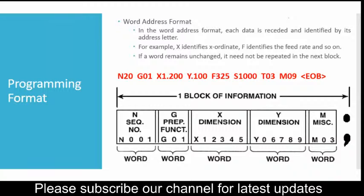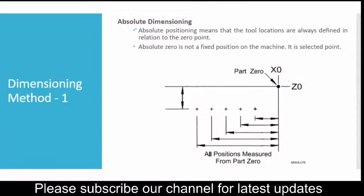Okay, now let us jump to the next slide. Now before starting, suppose I have to change tool. So every time offset measurement? No, before starting manufacturing, you must select the tools that you will be using throughout the program, and you have to take work offset for each and every tool. Okay, Kaushik?